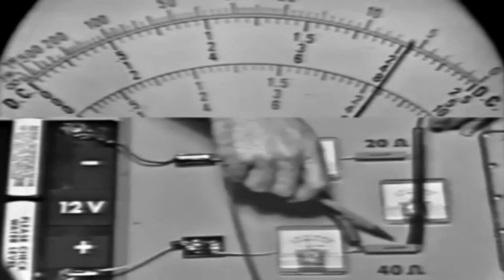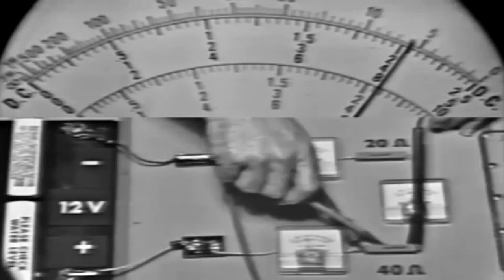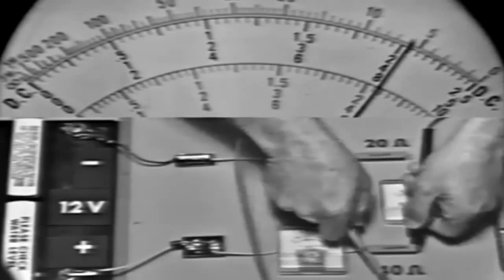Okay, here we get about, let's call it, 8.2, on the bottom numbers on the DC scale. We have 4.3 volts here and about 8.2 volts here. If we add these two voltage drops, their sum is equal to about 12.5 volts, or somewhere near the applied voltage. And of course, this satisfies Kirchhoff's voltage law.